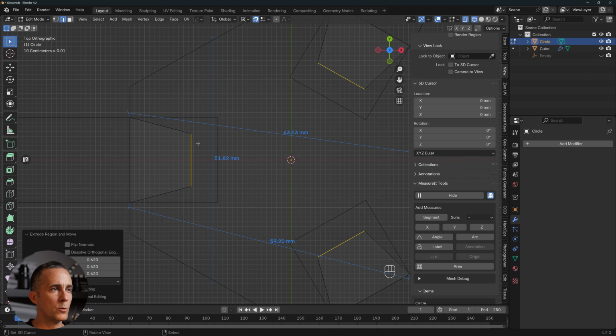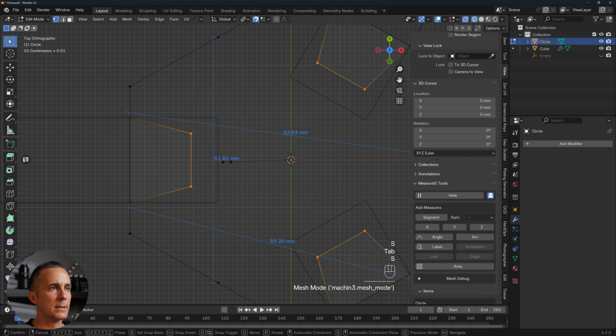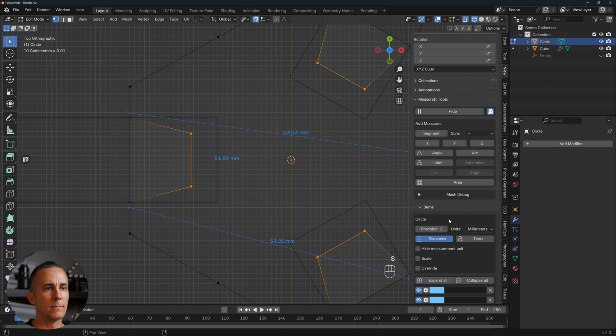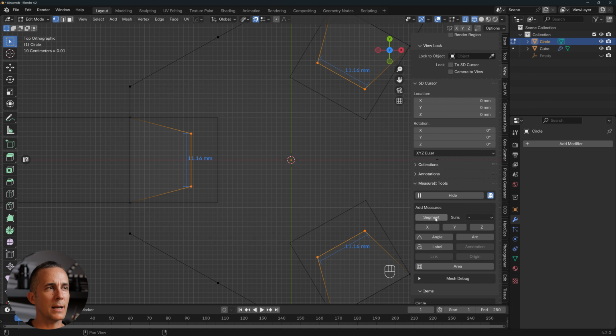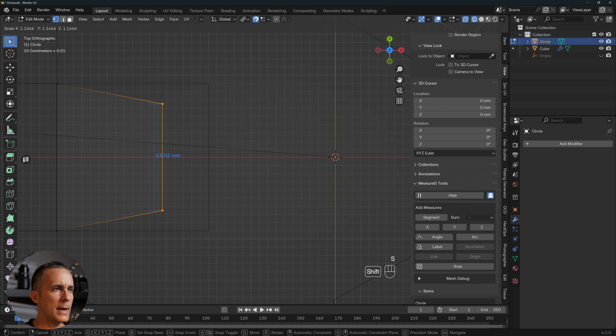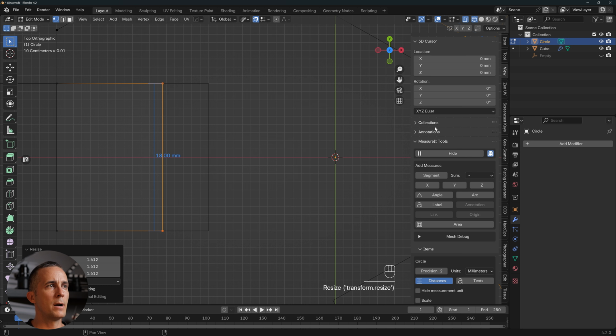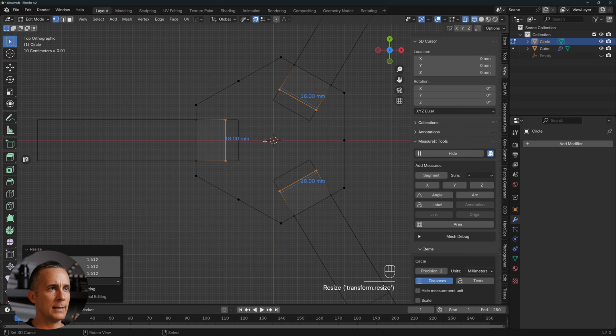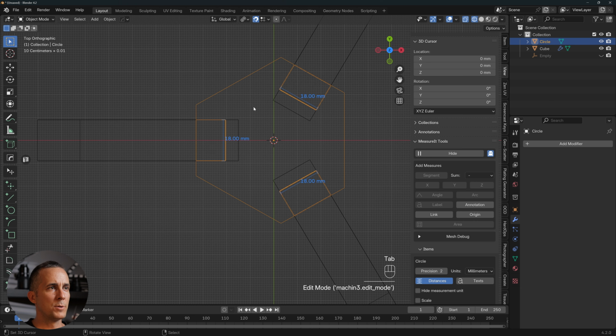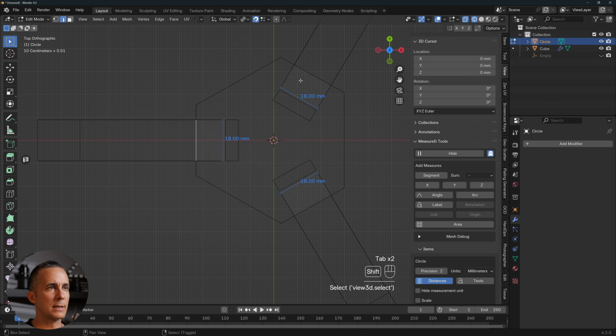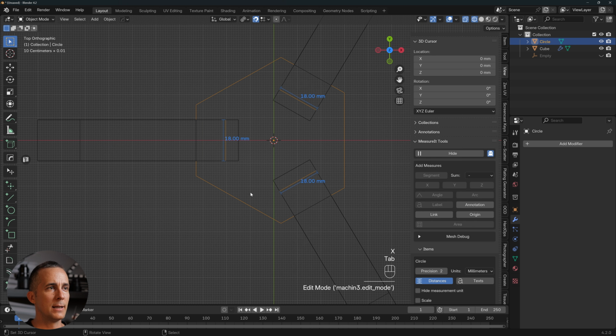And then I want to scale it again back to individual. Okay, S, and go to vertices, and if I delete this and set new segments, I want again to have 18. So something like this. Perfect. And let me see. Object, this is how our object looks. If we go right here and select this, this, and this edge by holding Shift and press X and delete edges, this is how it looks.